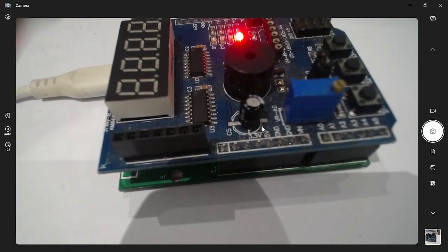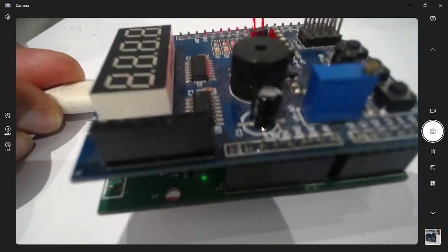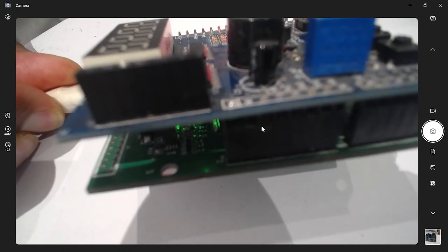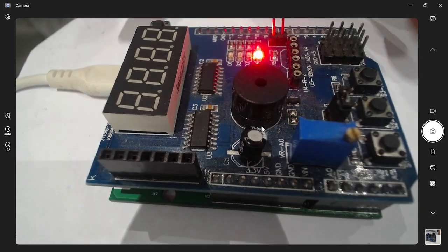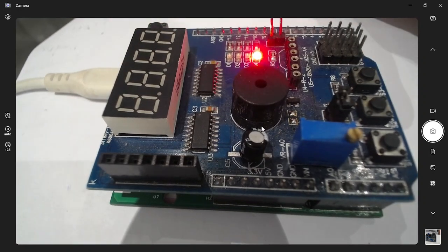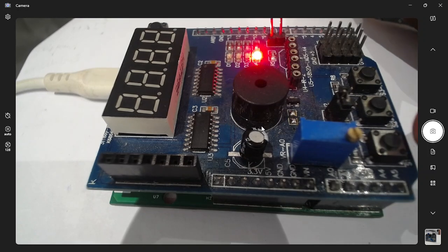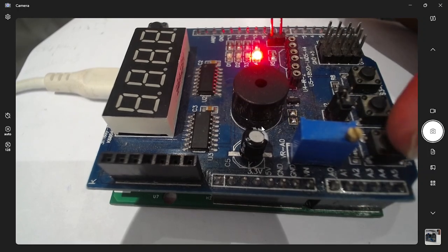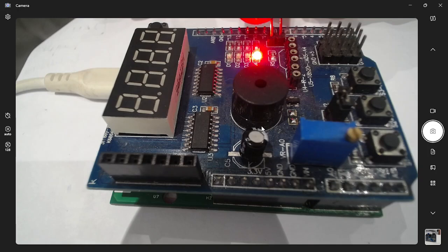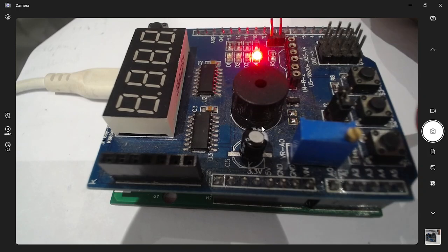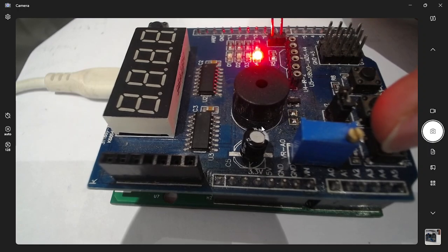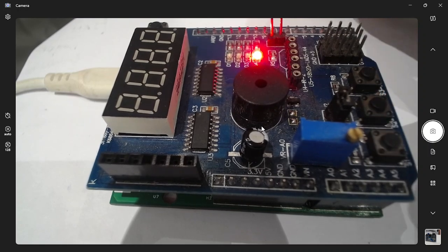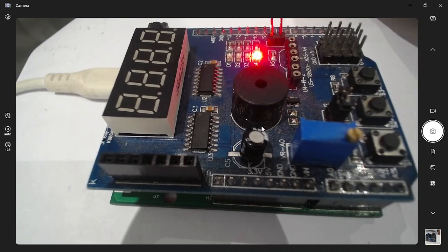I hope you guys can see it clearly. This is the Eklavya board, and we have interfaced it with the Arduino multi-shield board. Here, the input A, I've assigned it to switch one over here, and D4, the LED, is the output pin that I've assigned. Whenever the input is 0, we will be getting the output as 1, and whenever the input is 1, we'll be getting the output as 0.